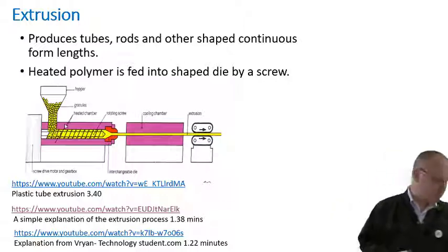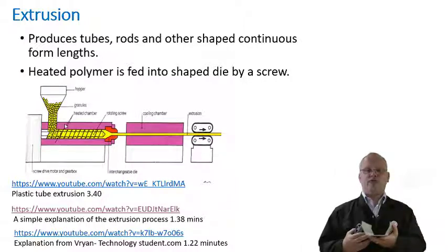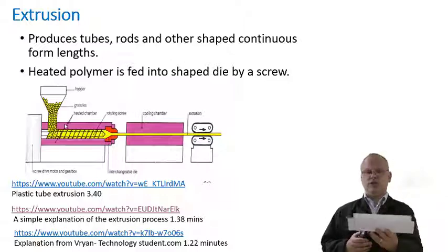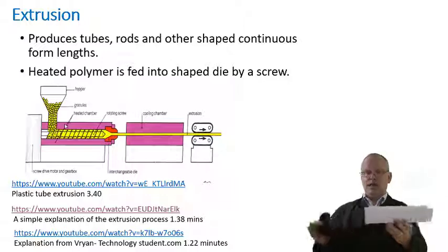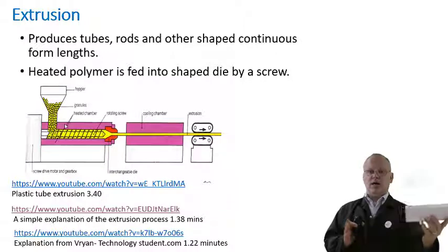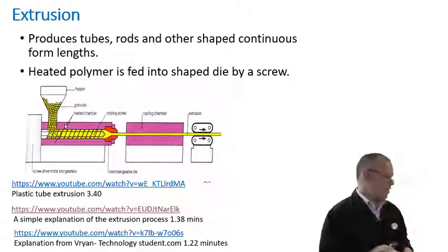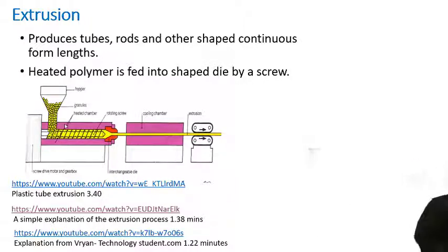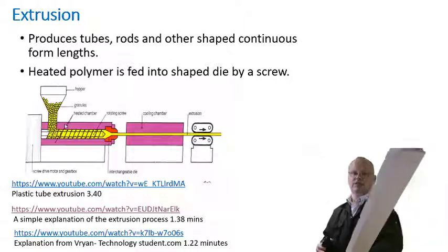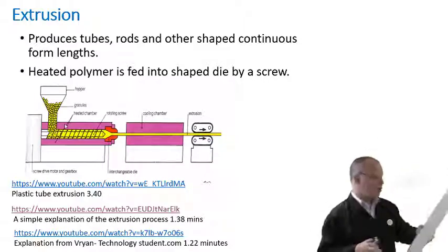So we've got our extruded pipe, another bit of extruded polyvinyl chloride here, so you can see the profile of that piece of guttering, and that would be continuously extruded. So these are bought in 2.5 meter length, 2.4 meter lengths, but that would be a continuous process. There is a machine somewhere continually passing out lengths of extruded gutter with that profile, and others. Okay, so that's the extrusion of that, and then another example. Okay, so here's a long piece of rectangular downpipe, or square section downpipe. So long, thin, hollow forms, very robust manufacturing process.